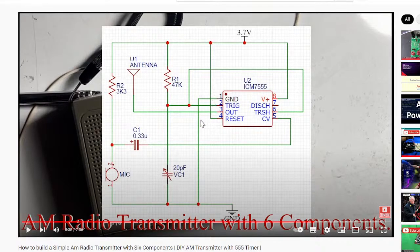Even though the wires are crossing, if there's no dot, it means there's no connection, they're just passing. Imagine this as a PCB, where some wires are on the top of the PCB and some are at the bottom; there's no connection even though the wires are crossing. Where there's a connection, you see a dot, like here and there. But for this area, there's no dot, so there's no connection. No dot, no connection. All right.